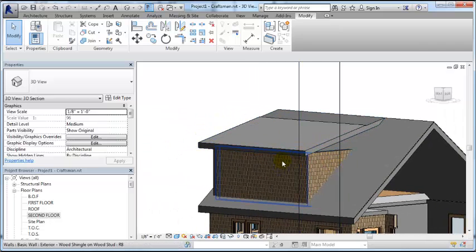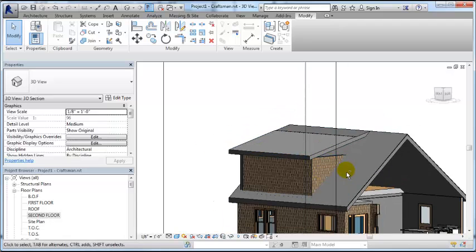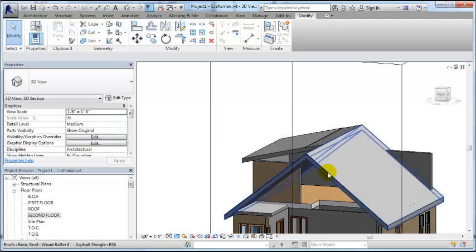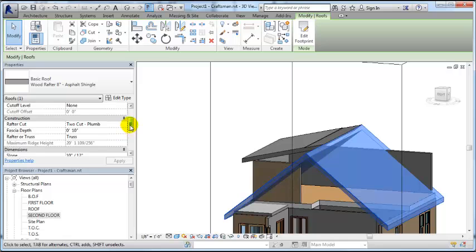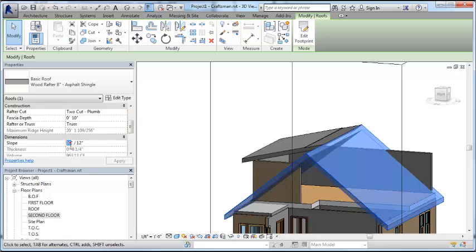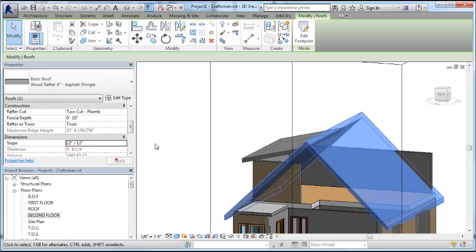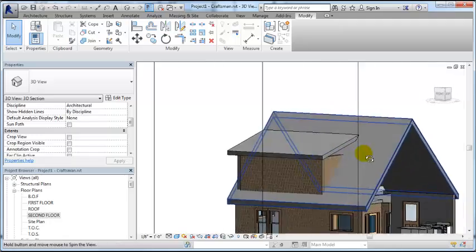I can lower this wall and still put in a ceiling at 7 feet or 7 feet 2 inches if I want to get that 7-foot finished floor to finished ceiling height, and just have this wall be a bit lower. So there would be just a slight slope to that ceiling on that side. Or the other option is I could select this main roof and change its pitch to a 12-12 pitch rather than a 10-12, and then I have no problem at all.